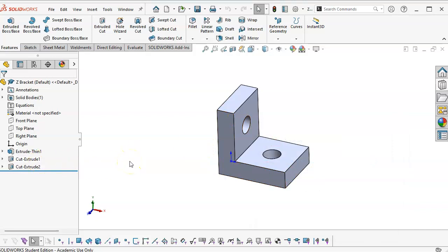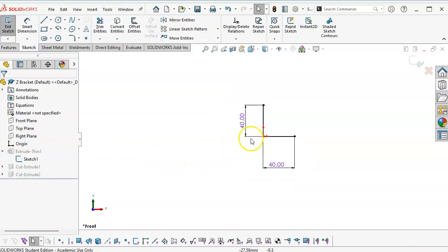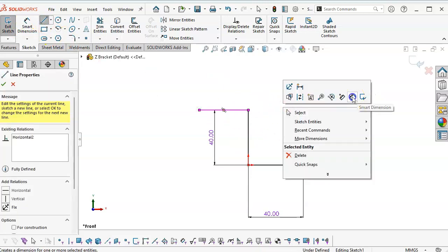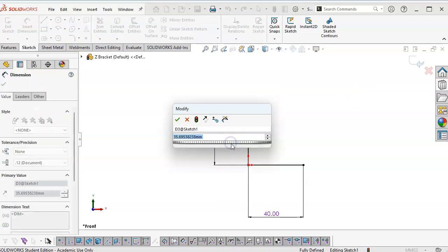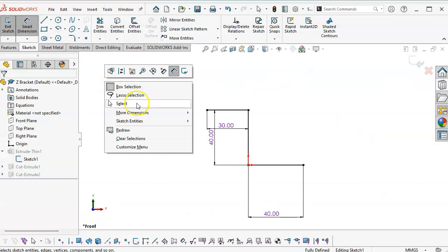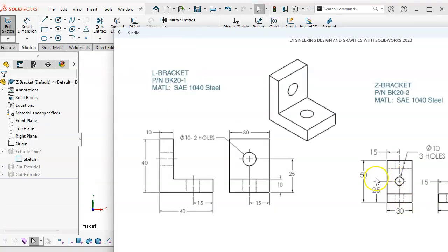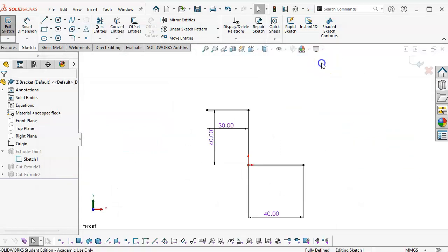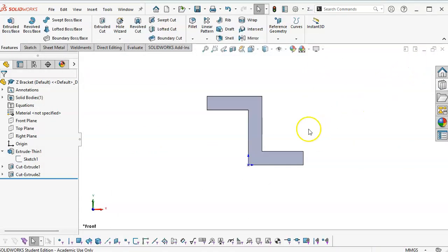All right, so if I stay with this grouping, then I want to open the sketch, and that was 30, and that was 40, and I'm still okay with the thin feature, but we do have to check some numbers. So 30, and then the overall becomes 50 because we added that other 10 in. I'm okay with that. Let's see, the 30 should, because it offsets that way and that way, we should end up with the 40 without any problems. So let's go ahead and hit OK.